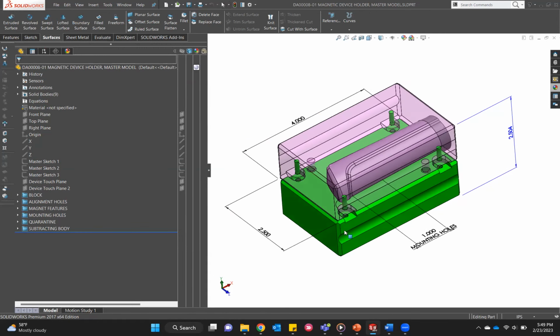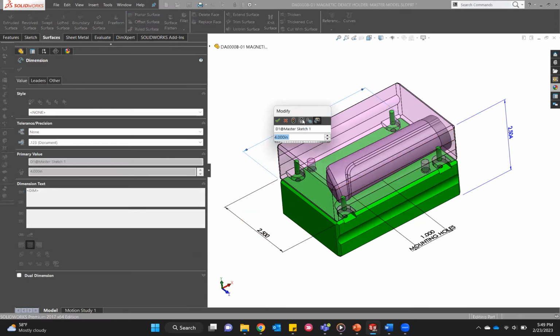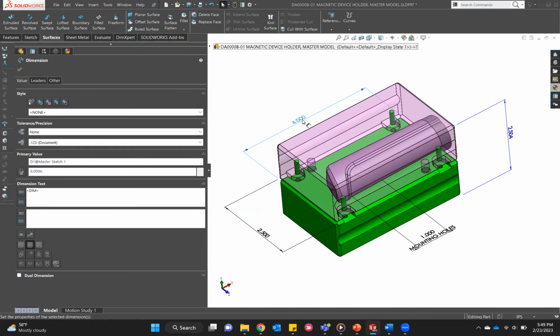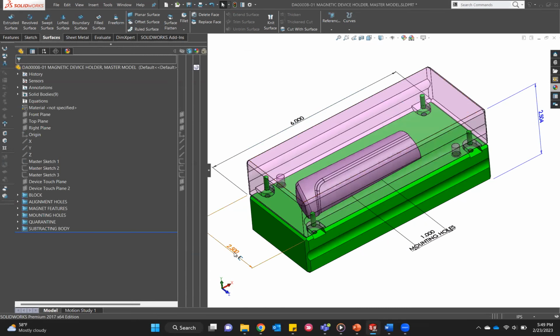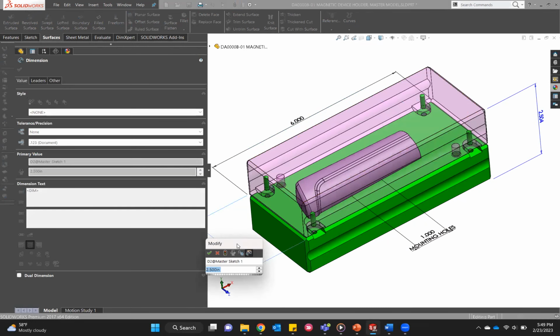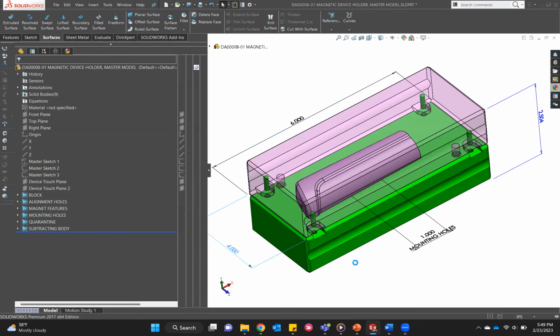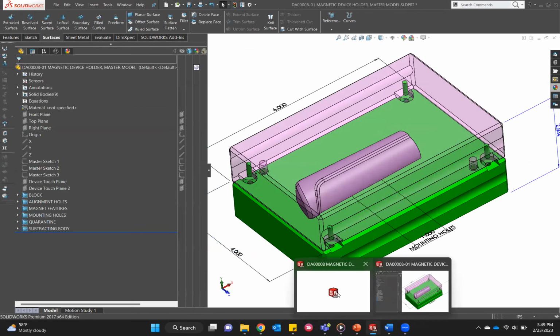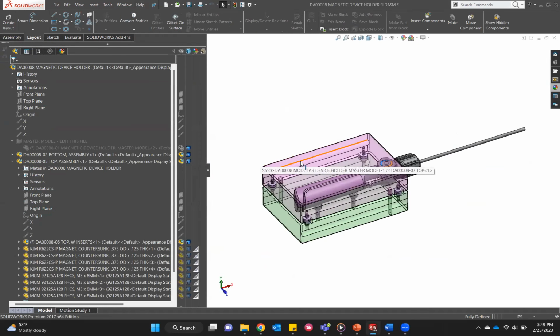So you're like, okay, I have a device that's not the mock-up device that's in here, and the device may need a fixture that's maybe 6 inches in length, right? So let's update that. Okay, there it goes. I rebuild it. And maybe the width is just a little wider, right? 4 inches. Now we go to the assembly, and when we update the assembly, it updates with that.